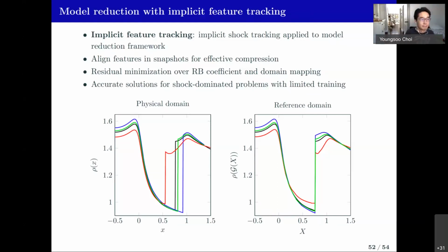Yeah, okay, so that's a great question. The optimization step is more expensive than a standard step. If you were to compare it side by side to one step of our SQP solver, and by the way, it's the same optimizer that we use for the ROM setting, with the exact same structure and the exact same solver, one step would be more expensive than one step of a standard pseudo transient continuation or Newton solver without moving the mesh, because you have more degrees of freedom.